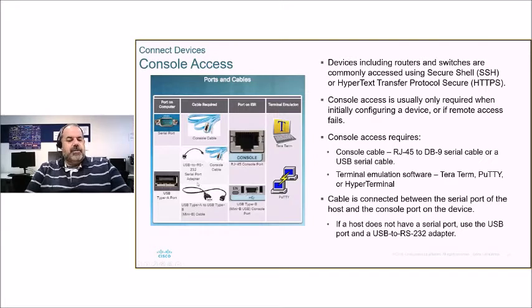Now you need to load a specialized driver to actually get that to work on the computer. And away you roll. And then, of course, you need software. Now there's Tera Term or PuTTY. They're the free options available. HyperTerminal used to be very popular as well, but it's actually not available for free anymore.